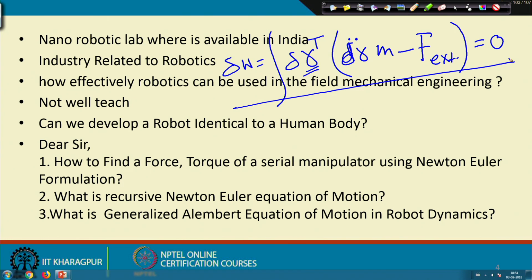In case of magnetic gripper, when you use electromagnet, in the time of releasing, why should you reverse the polarity? Is residual magnetism enough for lifting a heavy thing? Now, for this electromagnet, if you just reverse the polarity, there is a possibility that the strength of the magnetic field between the gripper and the object will be weaker, and due to the self weight the magnetic object will be separated out.